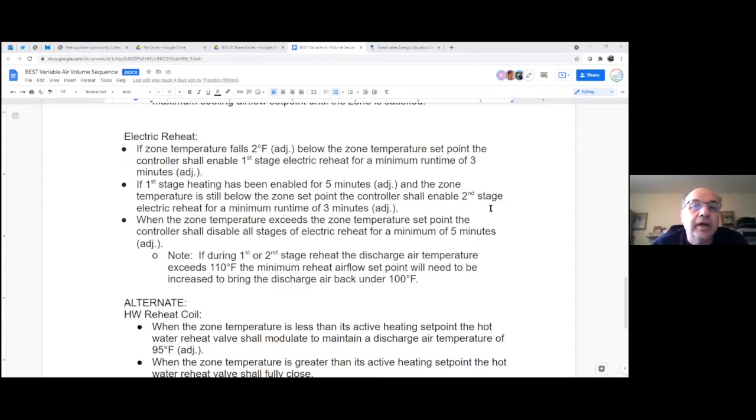Well, the point I'm trying to make also is, have the CO2 sensors gone down in price, where you could actually put one for each office? Because really, that's the bottom line. You want to have that CO2 minimum of some number of parts per million, so you have the fresh air requirements and not use up all that outside air energy. This is largely based on the 90.1 guidelines.